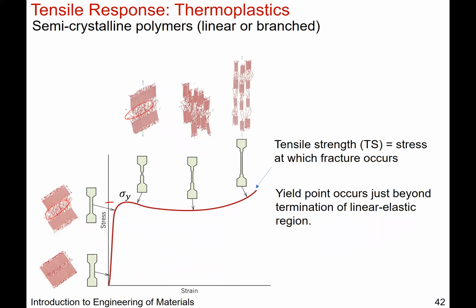And now you have all these strands that are in the middle, right? So you're applying some stress, there's some elongation, and then you continue to do so. The crystalline region right here mostly stays intact in terms of its length. This length right here, most of the time, is called T. They're elongating, but the amorphous spaghetti-like region is increasing, as you can see here.